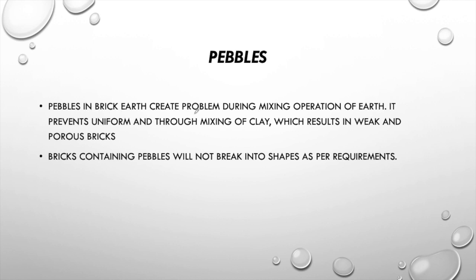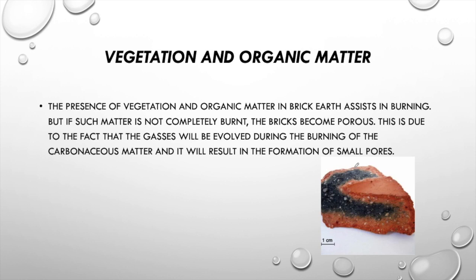Now, the pebbles are also a harmful ingredient. Pebbles in the brick earth create problems during the mixing operation, and because of this it results in weak and porous bricks after burning. So if the pebbles are present, then the bricks will lose their shape as per the requirement.